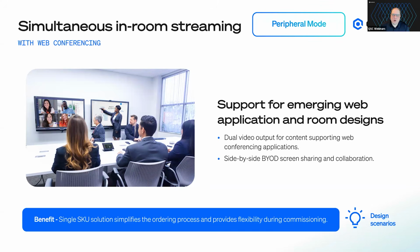So Sam, we had a question from Matt. Are there any gotchas with USB peripherals? Well, if you're talking about your connection to your BYOM device, maybe that's a Teams Rooms compute or a Zoom compute, the NV32 is USB 3. If you need to lower that down to USB 2, our device will work with that, but there is a chart within our help file that shows the available resolutions at those different USB speeds. So we absolutely recommend USB 3.